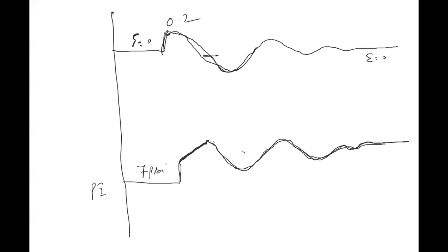So during this time lag, you might have opened the control valve a little more or closed the control valve a little more. So that makes the temperature go from 60 to 60.1. That is where, when you slowly open, slowly close, slowly open, slowly close, that is how you have an oscillatory behavior. Just take time and understand the system.